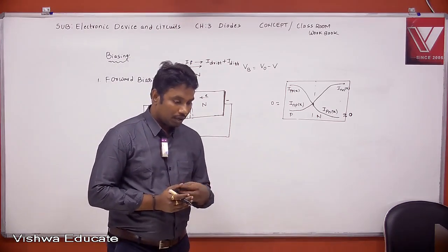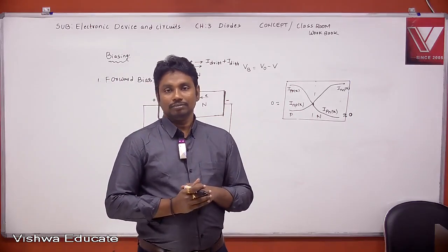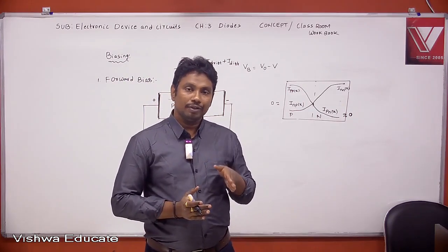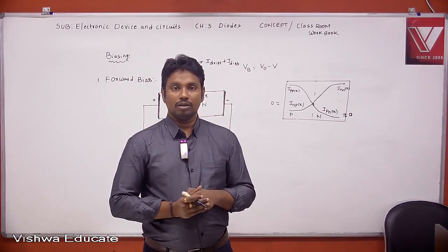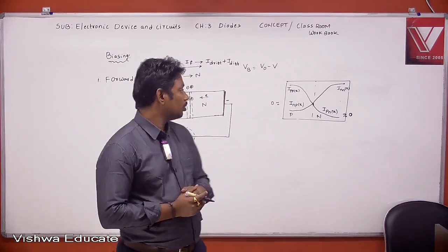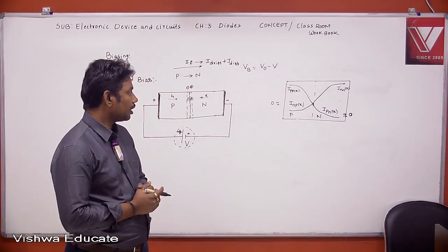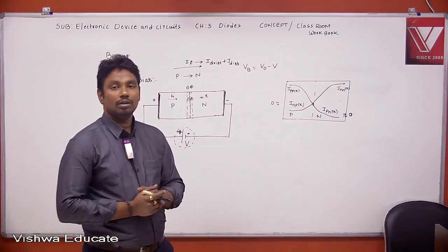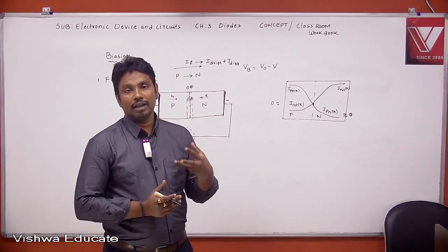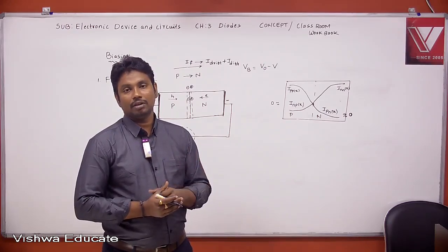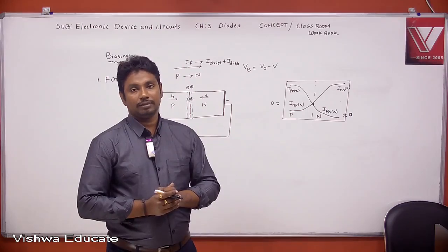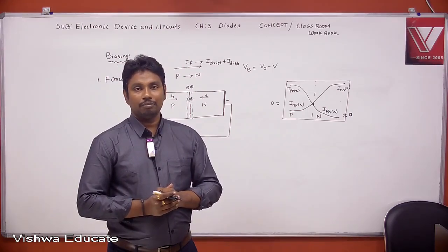Right, next point: due to concentration gradient at the junction, electrons will diffuse into P side, and produce a current INP of X. Next point: this INP of X becomes negligible at the far end of P side.